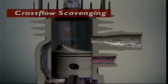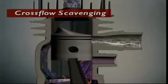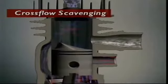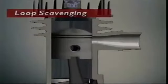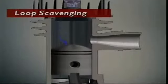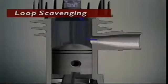How scavenging occurs depends on the design of the cylinder and ports. Crossflow scavenging occurs when mixture enters on one side of the cylinder and exhaust gases escape on the other side. No valves are used and mixture flows across the cylinder. Loop scavenging means mixture enters the cylinder across the top of the piston and is caused to flow upwards in a loop before moving in the direction of the exhaust port.